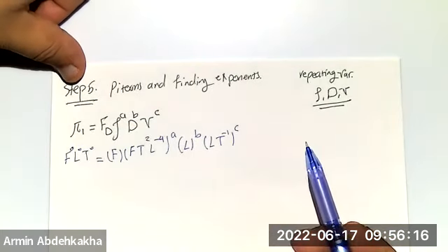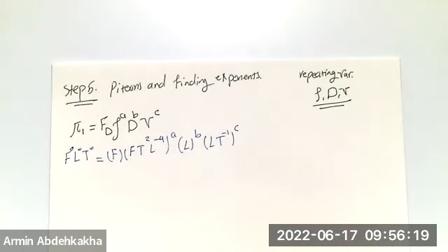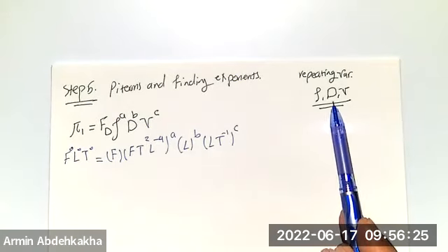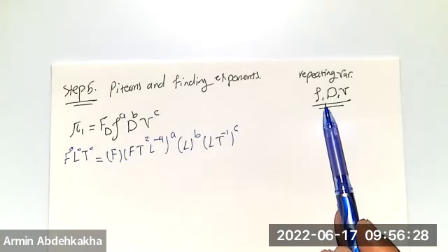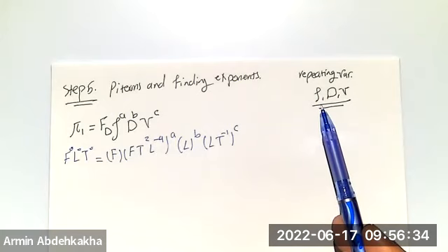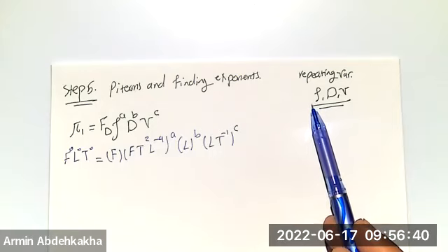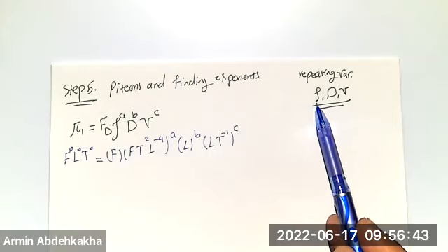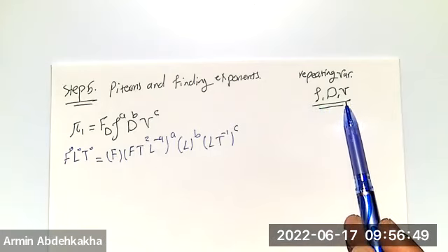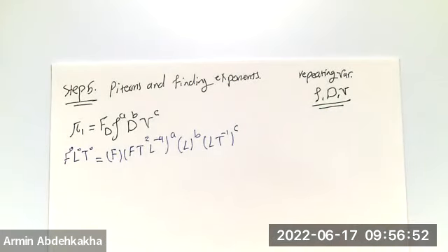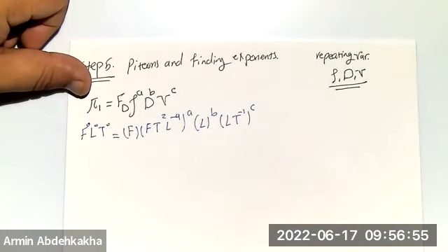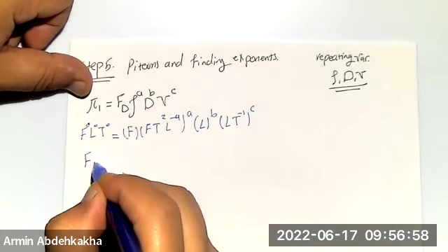Most general variables that could be said, you can say that most of the questions in fluid mechanics are dependent on the length or characteristic length of that material, like pipe diameter, pipe length, or for a ball, the diameter of the ball. And the density of the fluid is one of the most important. Absolutely, mu is also important, but most of the time rho is like mass. In any equation in solid mechanics, you need mass and also velocity. So these three are the most general ones. That's why we choose them.